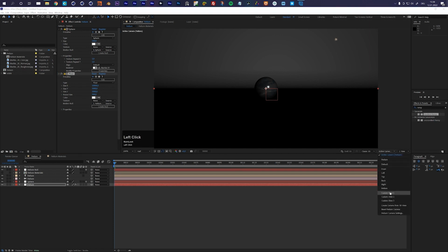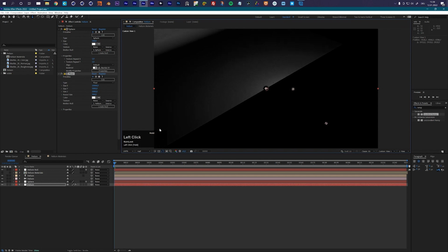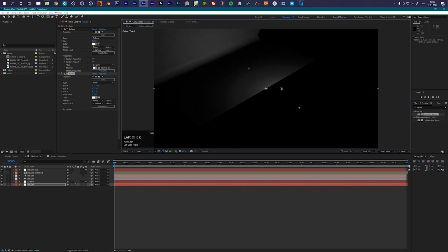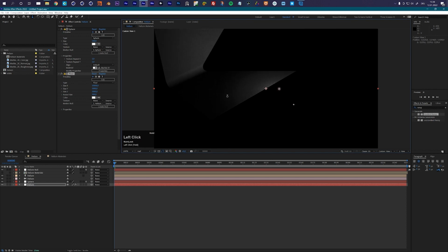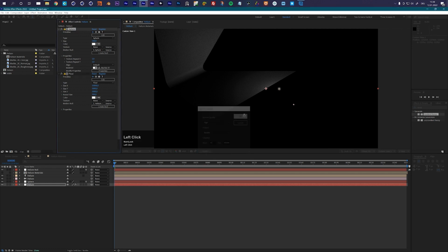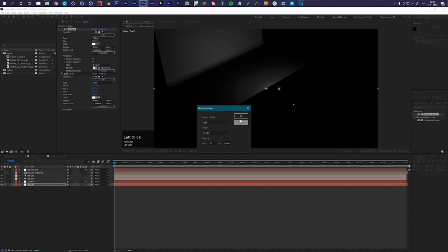And if I go now to my custom view, you will see, let me quickly dolly out a little bit, that we applied this backdrop floor here. And you also see that it is very huge, and it's already disappearing here in my Helium setting. And I think that this has to do actually with my settings. So if I go to the settings here, there is this clipping. I'm not sure, but I think that it has to do with that. Let me take a look whether this changes anything. Yeah, you see now I corrected this clipping here by just changing the clipping range here.